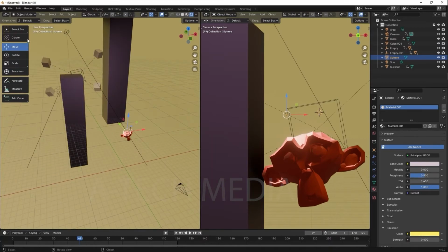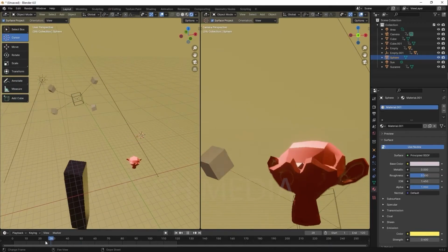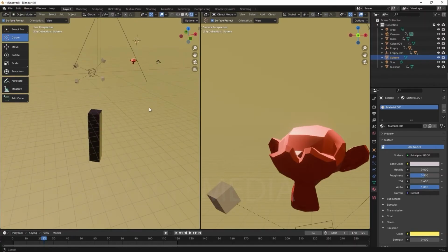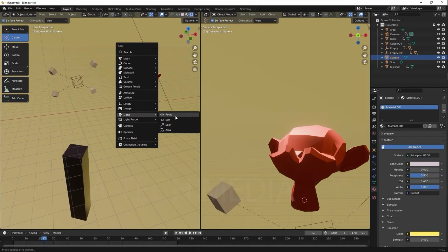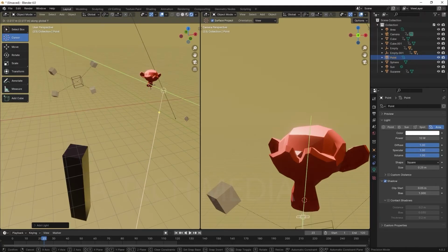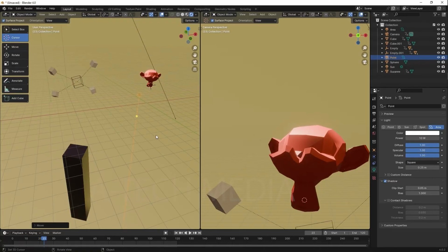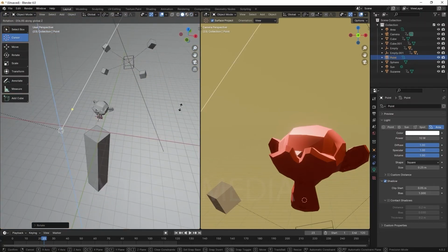All right, but if you notice, there are some very dark shadows around. So let's right click, let's add another light over here. Another area light. G grab, bring it out. G grab on the X axis. And now rotate it to make sure it's facing the monkey.